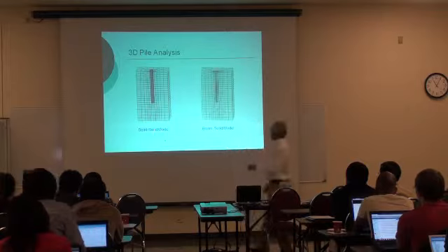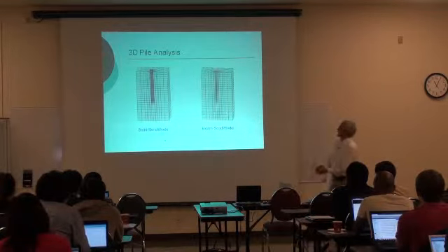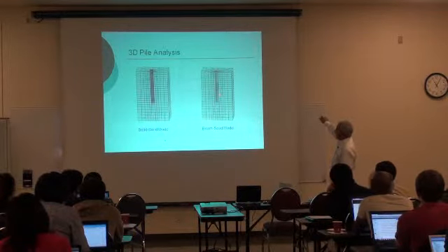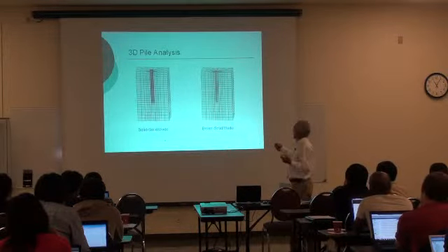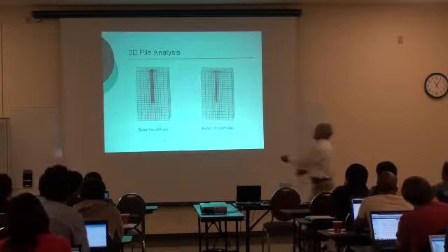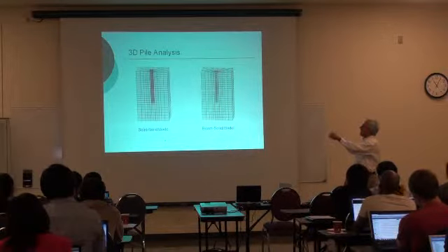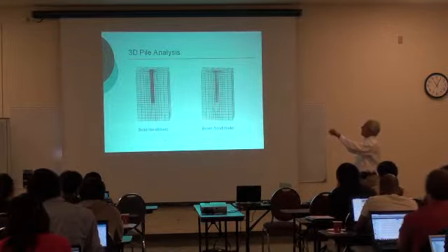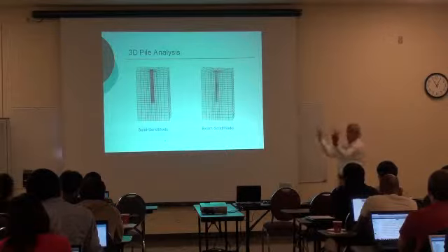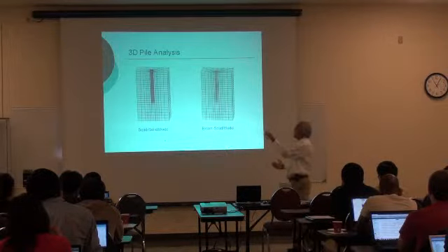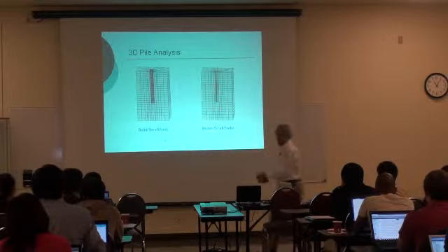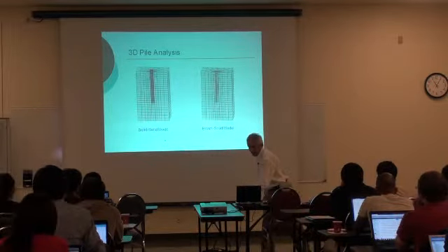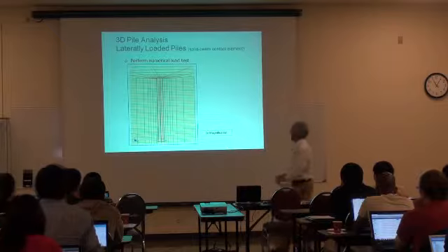Much easier to use a beam element, because the beam elements give me directly as a response the shear forces and the bending moments. So now, if you do that, you have to be careful, because if you use a beam model, you still need to capture the three-dimensionality of the interface. How to do that? Well, we did that using what is called the beam contact element that we developed.